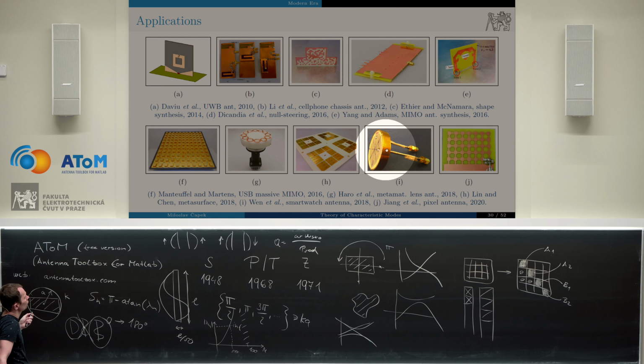You still have orthogonal far fields, and on top of that, while here you get a vector of characteristic current densities and you have no idea where to place your feeders to excite this current effectively, here on the right, you know exactly what to do. Because in your vector, which is of size 31 times 1, what is sitting inside are the excitation voltages for all these feeders.